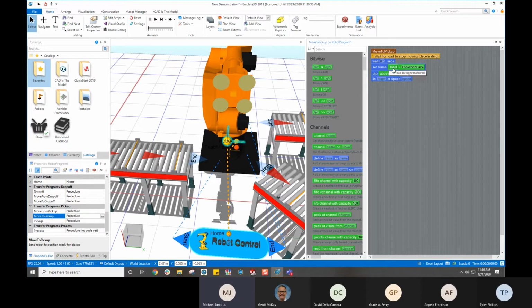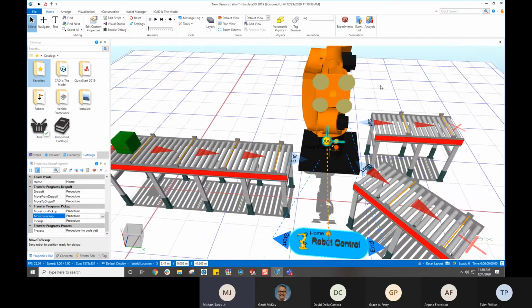And based on that weight, I could tell the robot joints to all run at a different speed. If it's a very light load, I could move the speed to one particular amount, and if it's between this mass and this mass, maybe a different speed, and if it's heavier than this mass, maybe it's a full stop and the robot just won't do it. So you can do that kind of thing, but the physics engine isn't managing that for you. That's more of an abstraction, an abstract kind of process that you impose over the system using the logic.